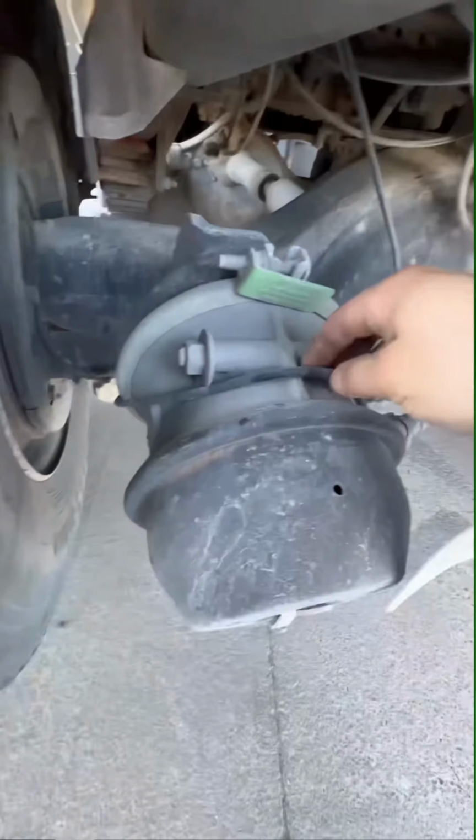And the issue with that? Well, in this case, the wheel bore is much larger than the hub itself. You see it? So if we reinstall the wheel just like any other wheel, it won't be properly centered on the hub, which will cause a vibration. You can balance the wheels 100 times, it still won't fix it.